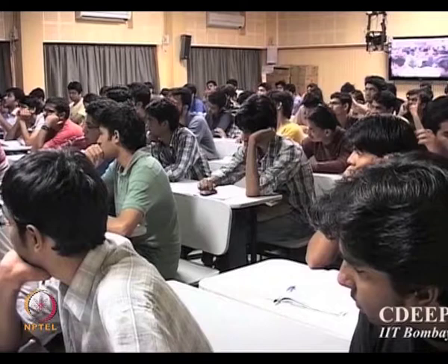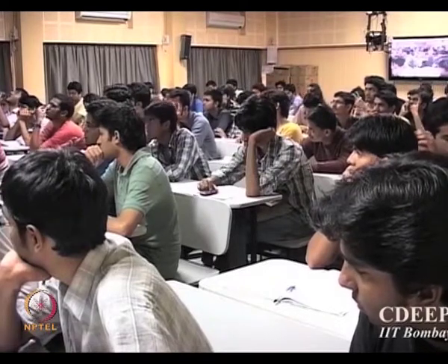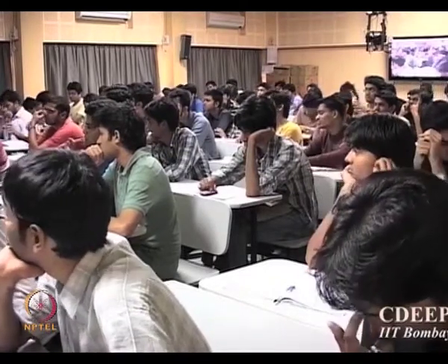But that is DC. That decides gm. Square root of 2 beta I decides gm. So whenever I fix I, I am fixing gm. Is that clear to you? Please do not get confused. AC signal theory is based on the DC values you fix. Is that correct? That is what we kept saying. RO is equal to 1 upon lambda times I, whatever I fix. gm is equal to the square root of beta times I. So once I fix I, I fix both gm and RO. Yes.